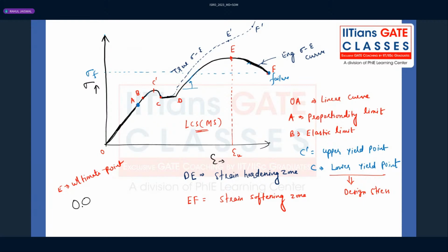If you incorporate more than 6.67 percent of carbon, it will simply come out, right? Because the maximum solubility of iron to accommodate carbon is 6.67 percent. That's why in the iron carbon diagram you will find up to 6.67 percent only.